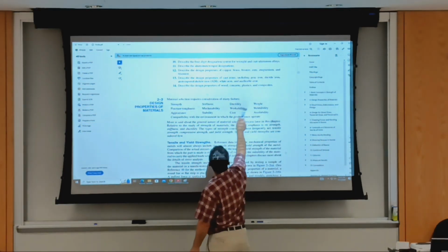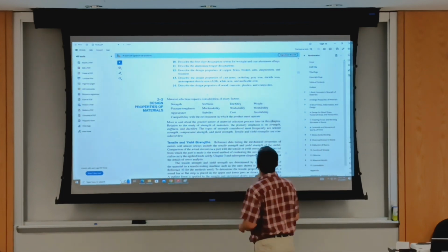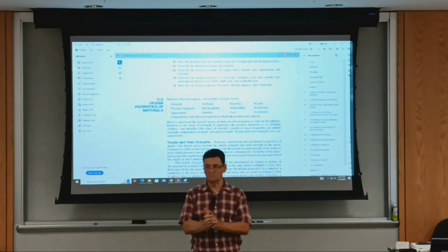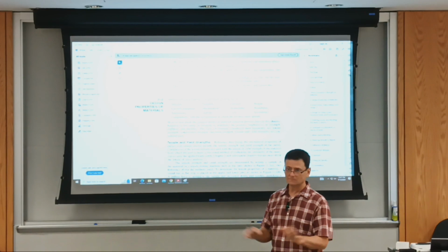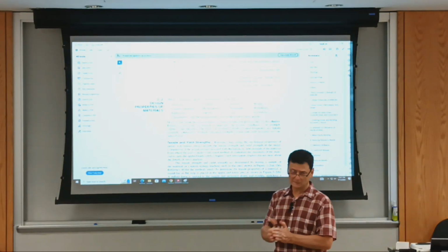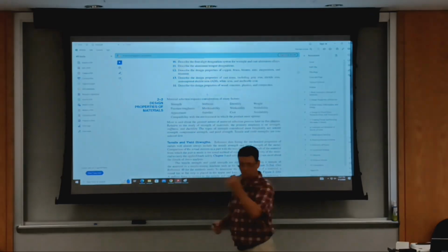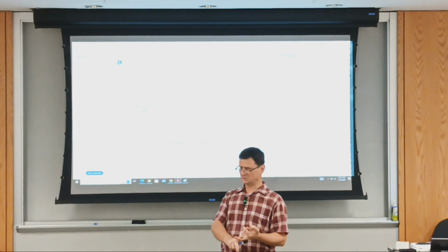Okay, workability is a general property that includes ductility, machinability, and then, can it be welded? Low carbon steel welds better. Medium carbon steel you can still weld. High carbon steel is very difficult to weld, although not impossible. Like if you go to a welder and say, weld me 2 files together, they'll look at you. Are you serious?